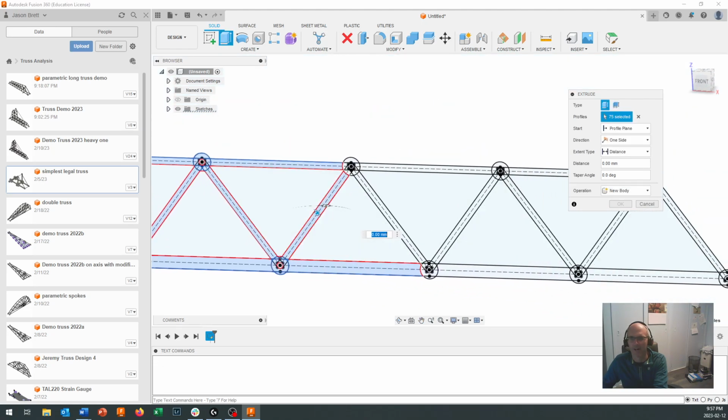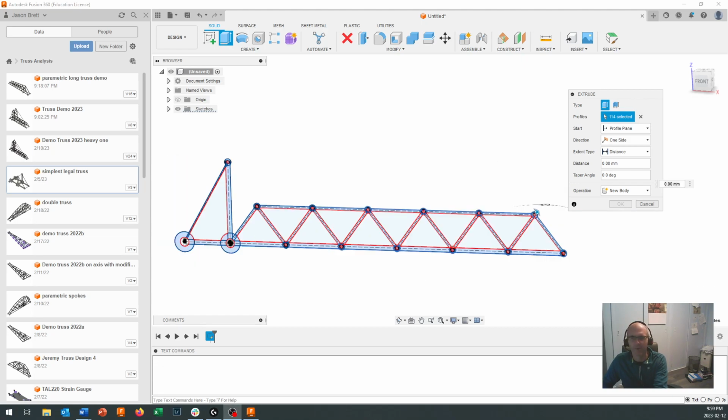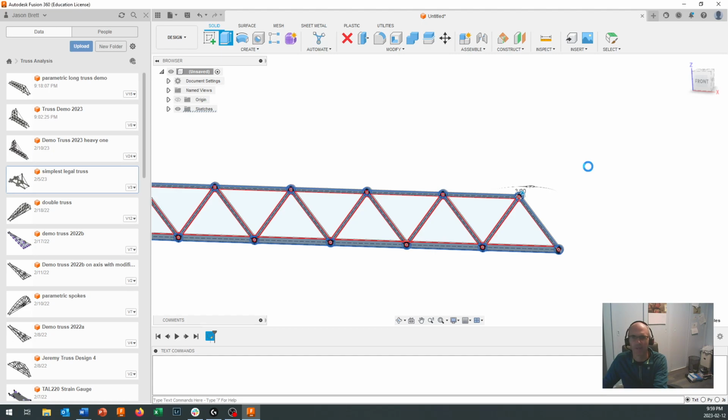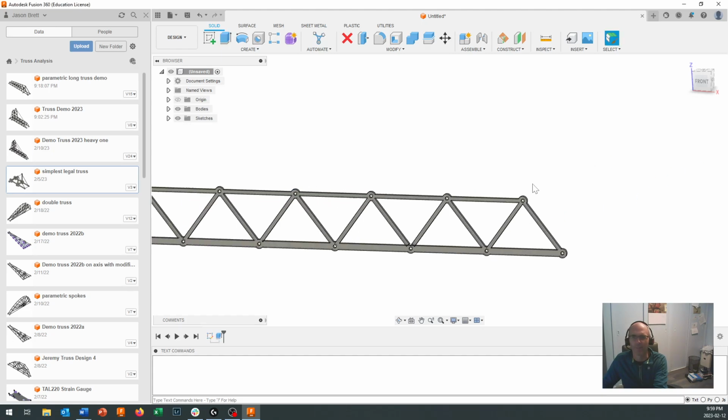Okay, I'm going to finish this off, and I think you've got the idea of picking out all those circles in the middle. I've gone through and picked out all of my circles, and I am going to extrude this 3 mm because we're cutting it out of a 3 mm piece of MDF or hardboard, as the case may be. There we go, 3 mm.